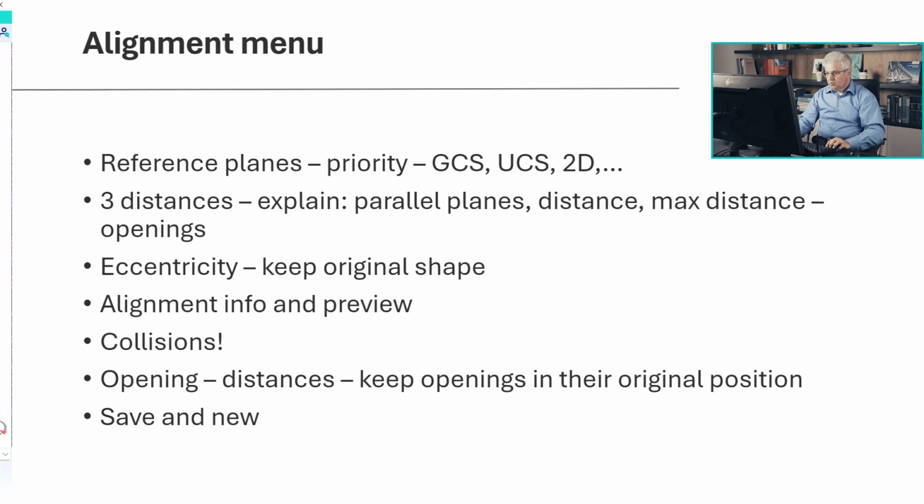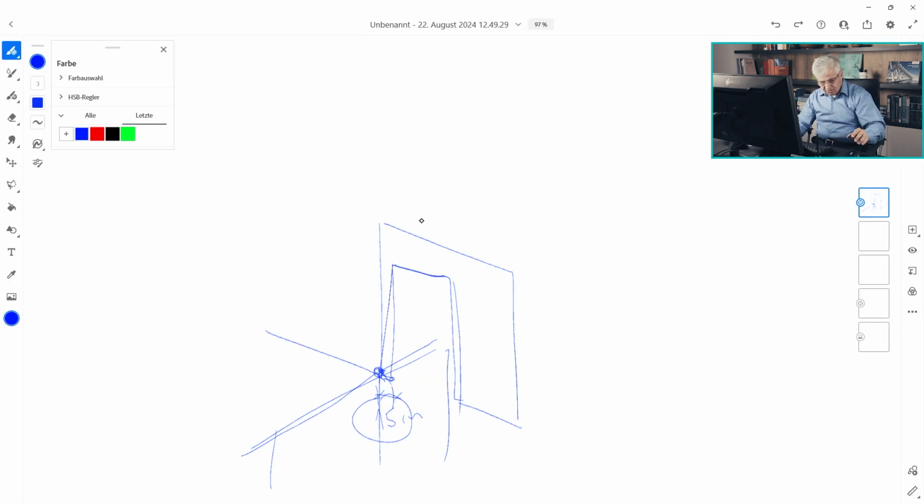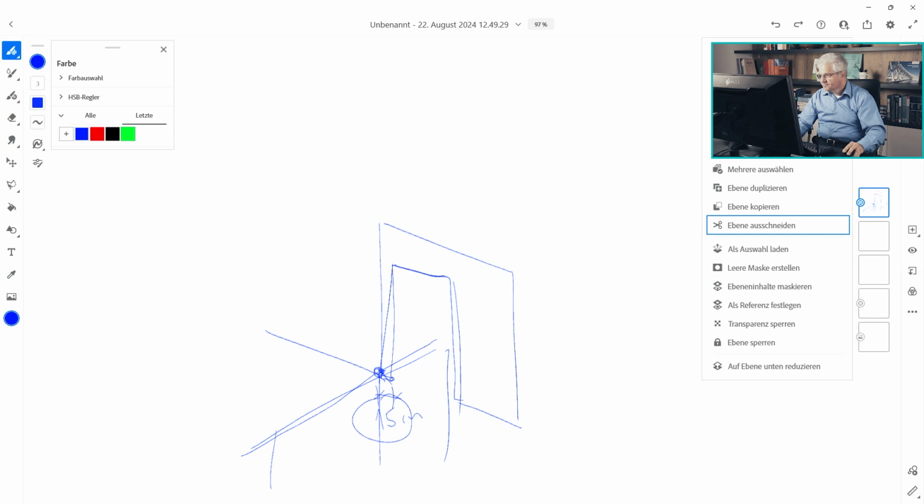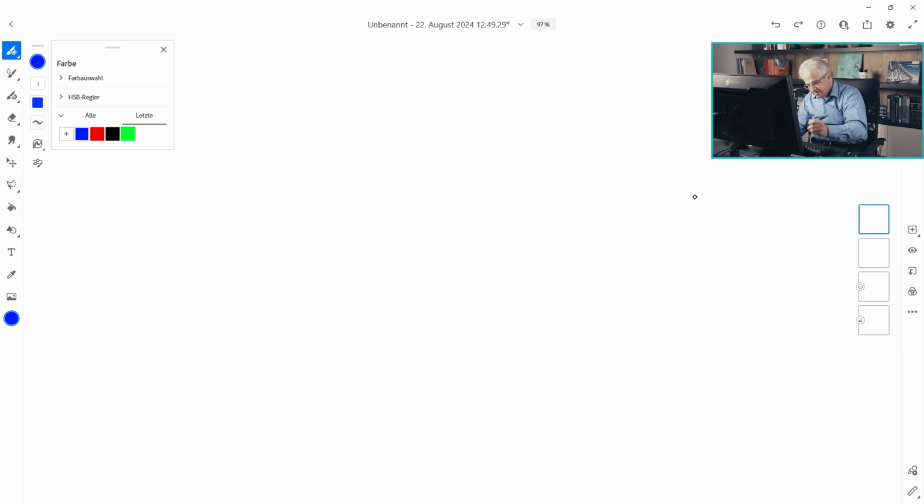In this case, you have to be careful in one situation. This is if you have a wall and you have a plate, and then you have somewhere your rib or some member. This is only one member. If you select everything, then SCIA Engineer has to decide whether this member should be a rib to the wall or to the plate. It has to decide for something. Sometimes it will be moved to the wall, and this is not correct.